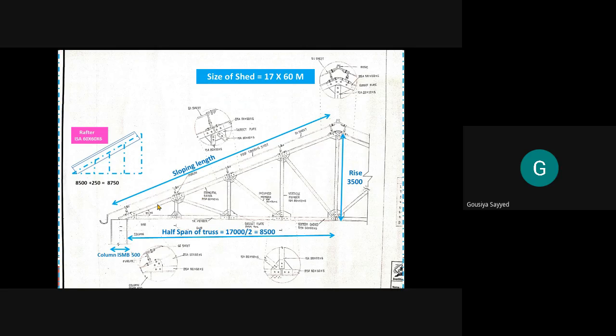And after that you have to show the gusseted base. And in this case, after drawing this half roof truss, you have to make an enlarged view or zoom view of this joint. Likewise here, again this is joint details at the ridge. This is joint details for the tension member connecting strut and sling. Okay, is it clear how to draw the half roof truss?